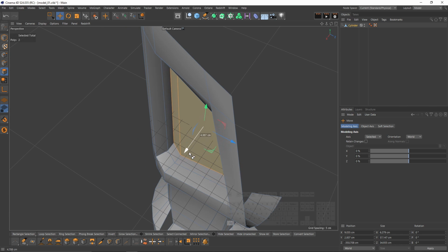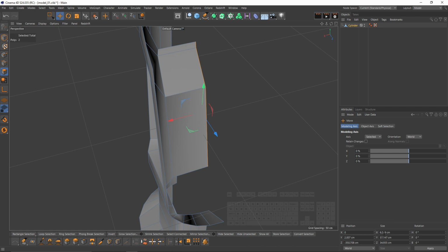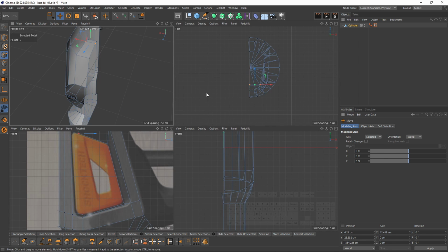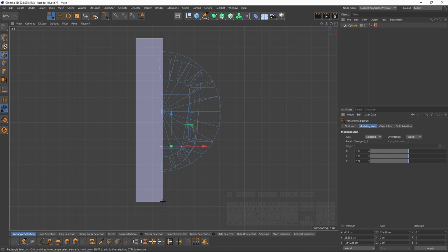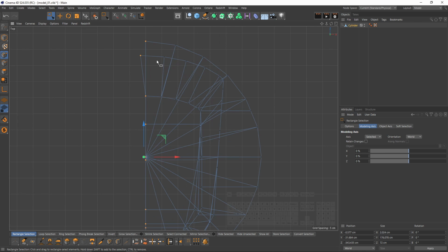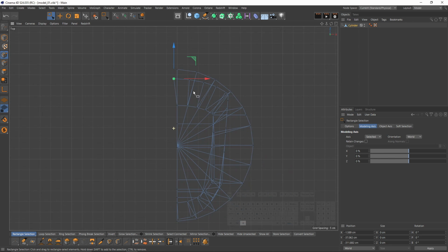This time I'm going to extrude these, press Ctrl, extrude, but I will set my X position and size to 0. Then I will delete this. I did this because I'm gonna use symmetry and I want these center points to be exactly right on 0 on both position and size. And I see that one point is off.